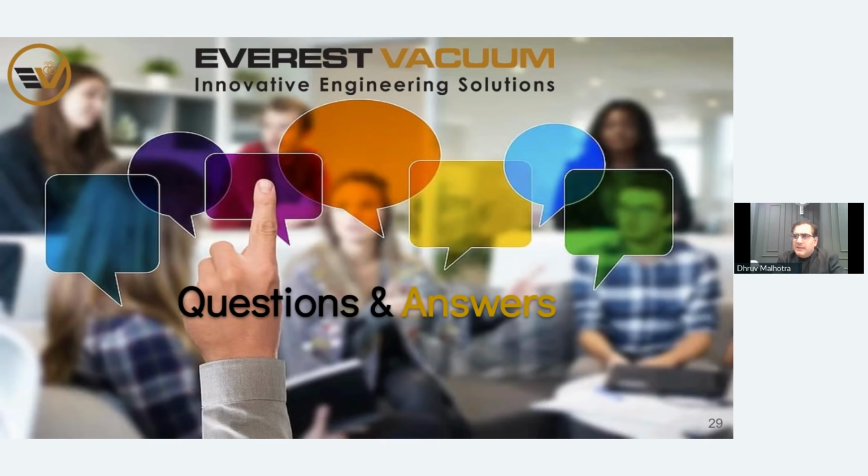So there is a complete pre-checklist of requirements that we share with you. There is a requirement for foundation from your end. The machine needs to be on stable ground. It's a complete skid-mounted machine. There is a requirement of a consistent electricity source, and apart from that, there is a requirement of cooling water in the intermediate condenser. Apart from this, there is no other requirement from the utility side when it is in process.